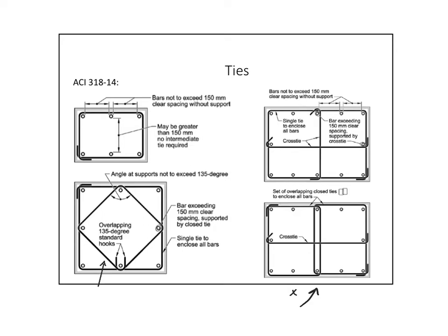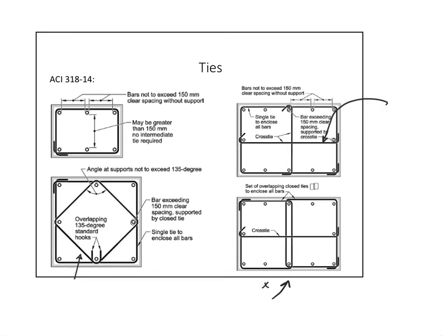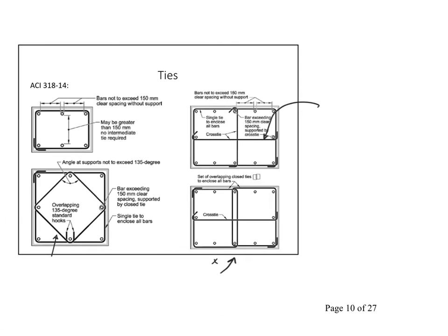Such bars are really good and nice and handy. It allows for the placement of the concrete inside the column very easily. Those cross ties are really easy to place, right? They can be placed after the ties are placed. A lot of times we alternate the cross tie hoops, but it's an important question here: why do they look like this and not look like this?